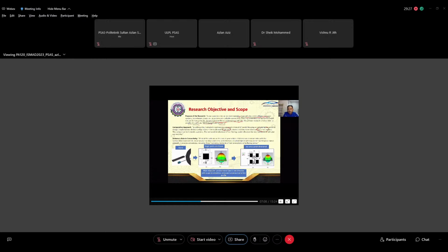A well-designed antenna doesn't just improve signal strength, it ensures consistency and reduces those frustrating moments of lost connectivity or buffering. So basically, the whole idea is changing from the omnidirectional antenna currently implemented to the proposed single patch antenna. This is our first contribution, and the second contribution is the 2x2 array, enhancing the single patch. The main objective is to provide more gain in one direction, with a scope on simulation and patch.